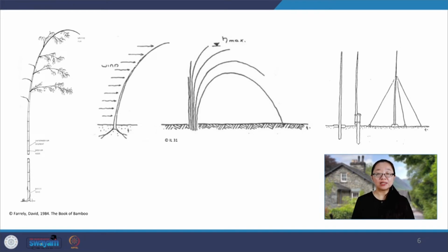From the age of 2 years, the canes can be used for making plank boards, and at this age, the bamboo canes are more flexible. Normally, between 3 and 5 years, the lignin of its tissue becomes as hard as wood, but still flexible and light, and thus is ideal for use in construction. Due to its favorable mechanical characteristics, great flexibility, rapid growth, and light weight, bamboo is used extensively as vernacular building material with many applications.